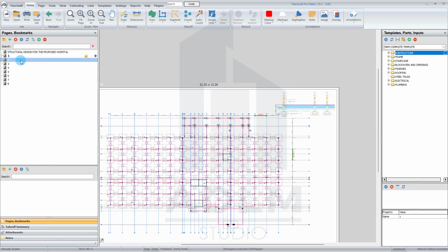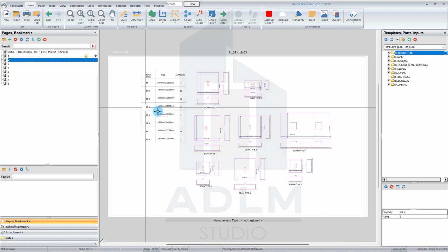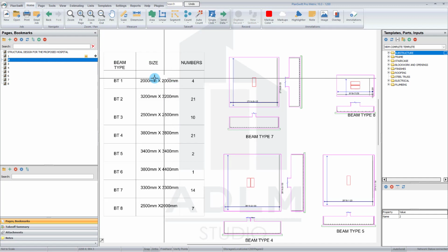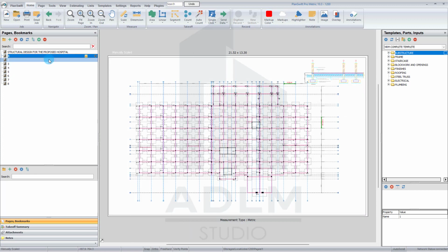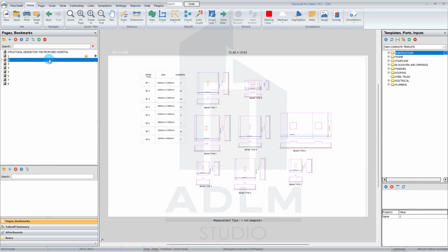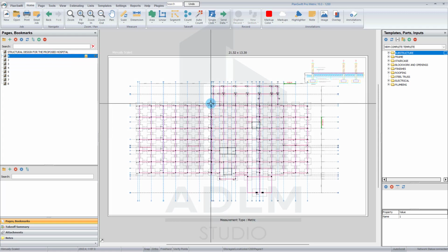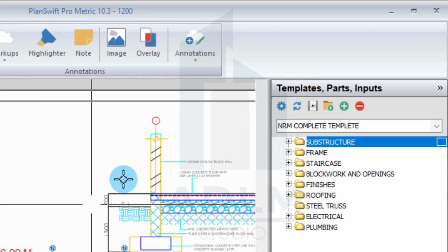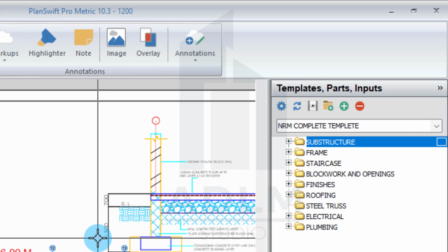You have to go through the drawing to check whatever information we have. Yeah, now we have the column base schedule down here also. This will help you instead of picking directly on the drawing like this. It will help you just pick with the schedule. Now the ADLM plugin has two features here. It has a feature for if you'll be using the area to pick directly on the drawing like this, and if you're going to be using the beam schedule, for those that might be lucky enough to have a beam schedule. Now since we have the depth of our excavation as 1.3 meters, right?